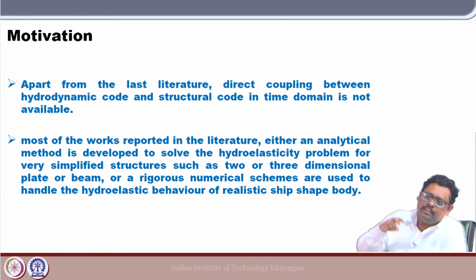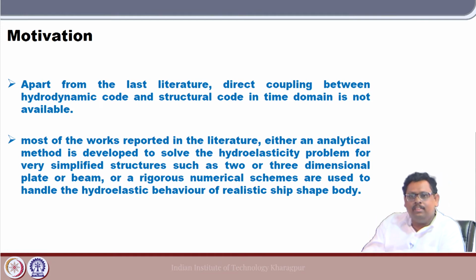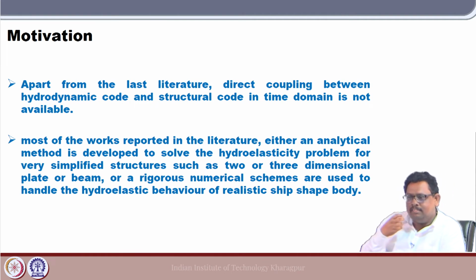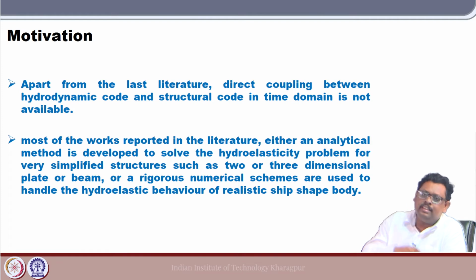For example, in this course we stopped with incorporating slamming and green water into the hydroelasticity solution. Now, this green water or slamming is not periodic in nature, it is an impulsive load. Once this is an impulsive load, handling it in the frequency domain is really difficult.